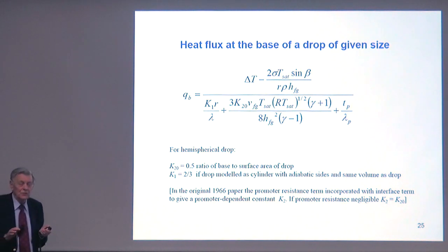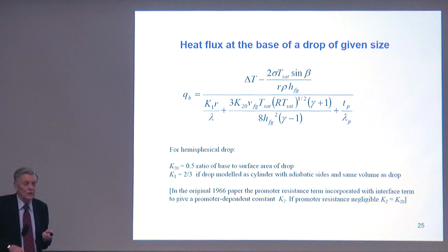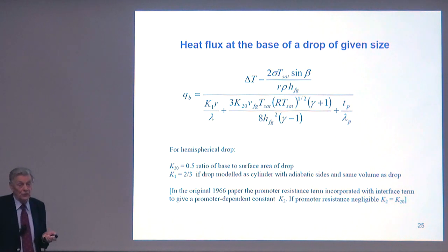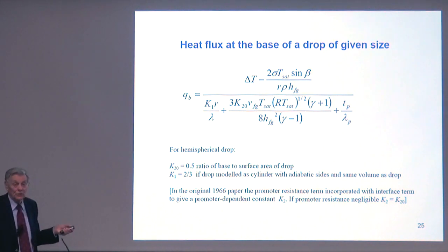Because of the extremely high condensation rate on the very small drops, the so-called interface matter transfer resistance is important. There is a temperature drop within a few mean free paths in the vapor, and this is an expression for that temperature drop based on kinetic theory of gases. In most applications, this is negligible, but in dropwise condensation, it plays a significant role.